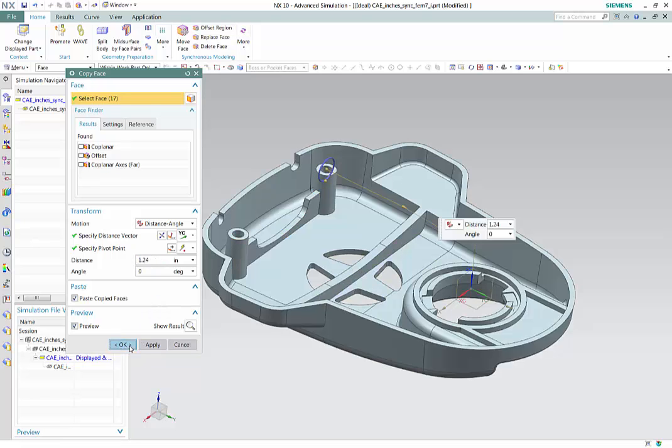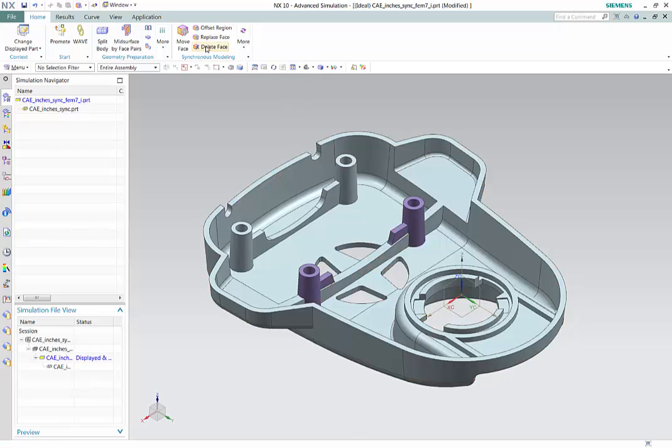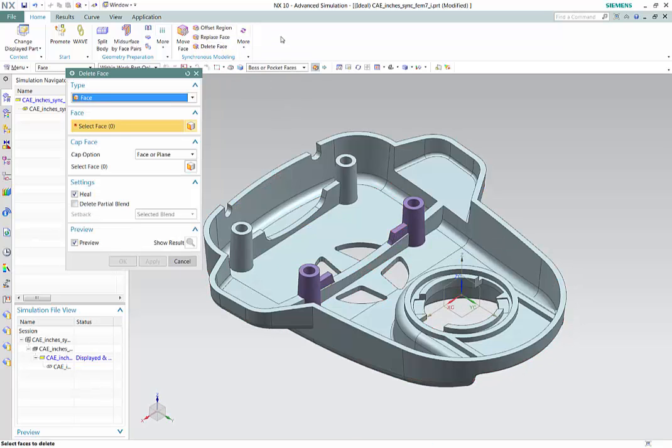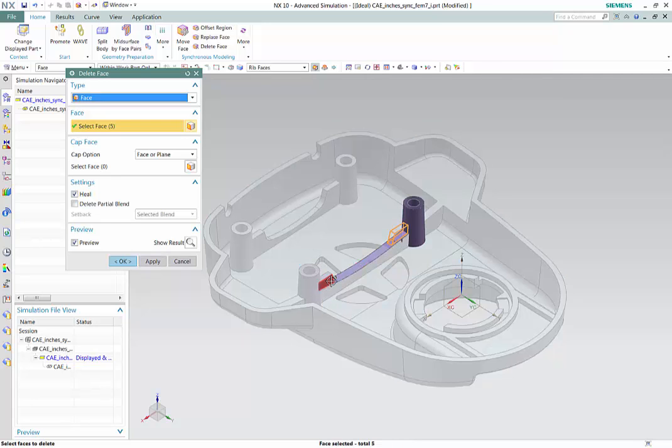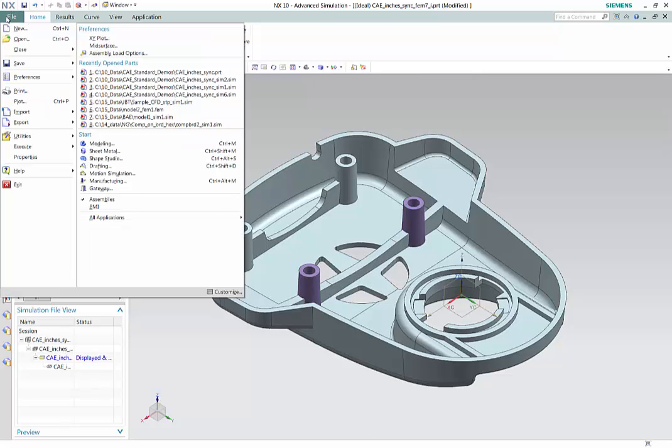And we'll put that in this location, except for a slight change this time around: I'm going to delete these extra little ribs that came in with the move, since I already have this other tab there that it's sitting on to give it additional strength. So I don't really need these small ribs. I'm going to set my faces. I'll select both of these ribs, delete those, and then we're ready to go and do our updates.